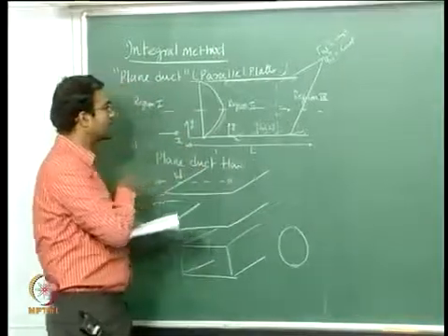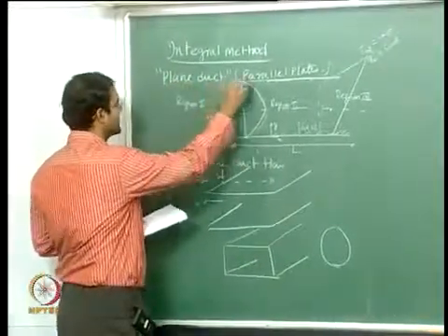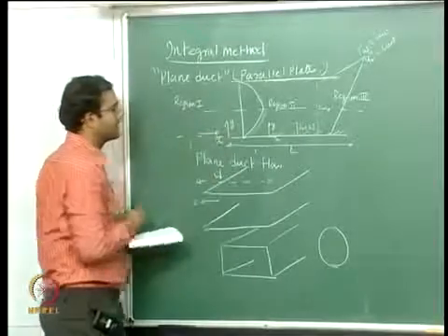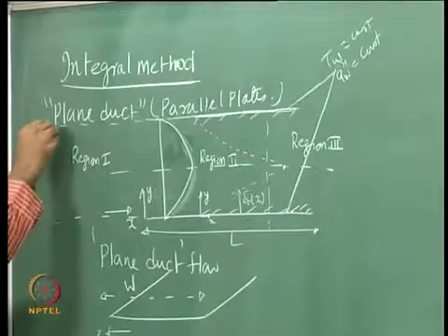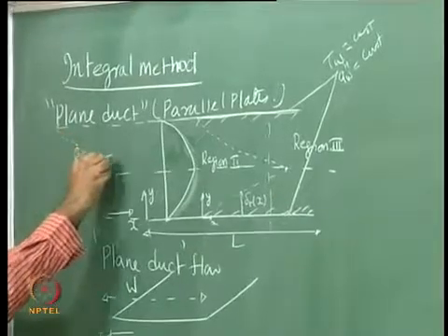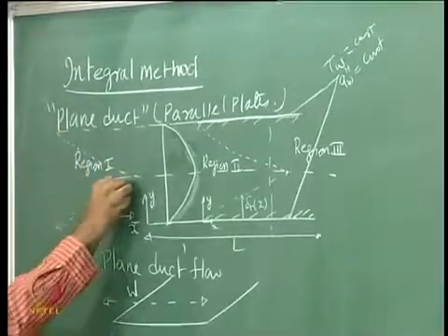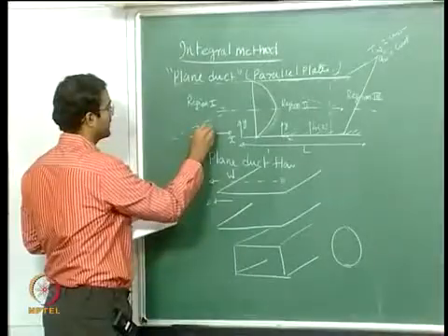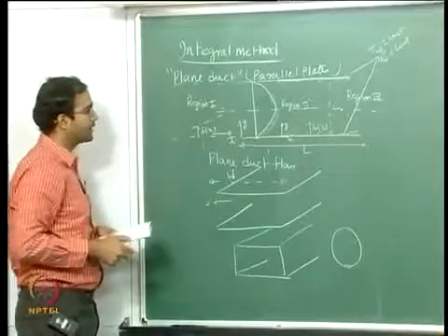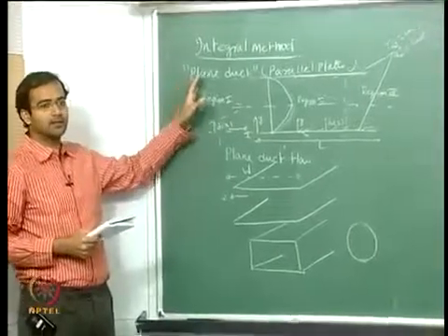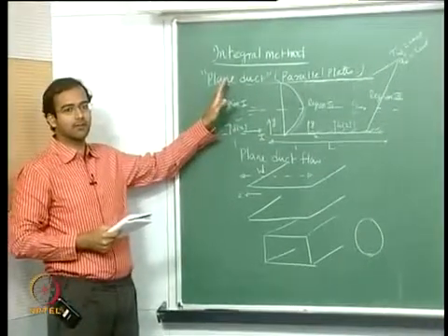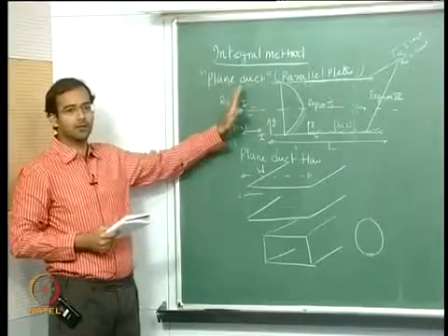Okay, so these momentum and energy integral approximations can be valid. Same way if you look at region 1, if you go several distances ahead, you can find the momentum boundary layer also starts developing here, and once again you can apply the momentum integral equations for the place where the momentum boundary layer is growing.